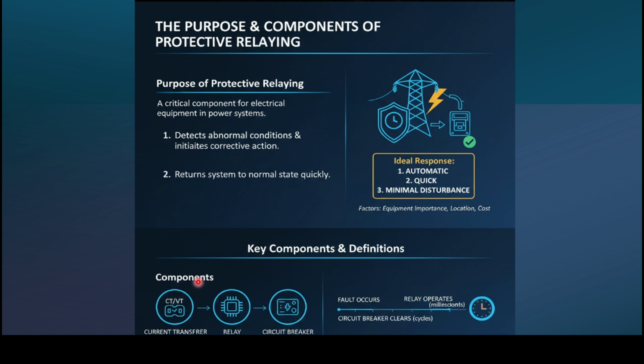Okay, so as we understood here, this operation is done with a circuit that's called a trip circuit, and these are the trip circuit blocks. The first component is a current transformer. Because these systems have a very big amount of current, we can't connect the relay directly. Our second element here is a relay.